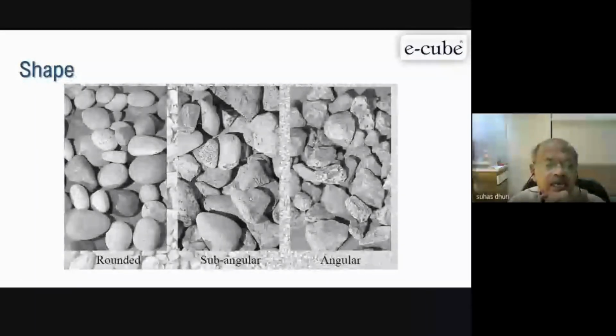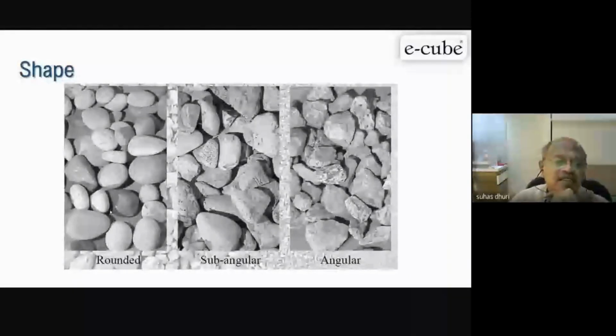See, these are gravels, rounded gravels. This is subangular gravel, but it is crushed, some of the aggregates. The same gravel comes from river beds. If you go to the Himalayas or Punjab, that area, most of the aggregate comes from the rivers, which have those aggregates there. They just screen this aggregate and use it in the concrete.